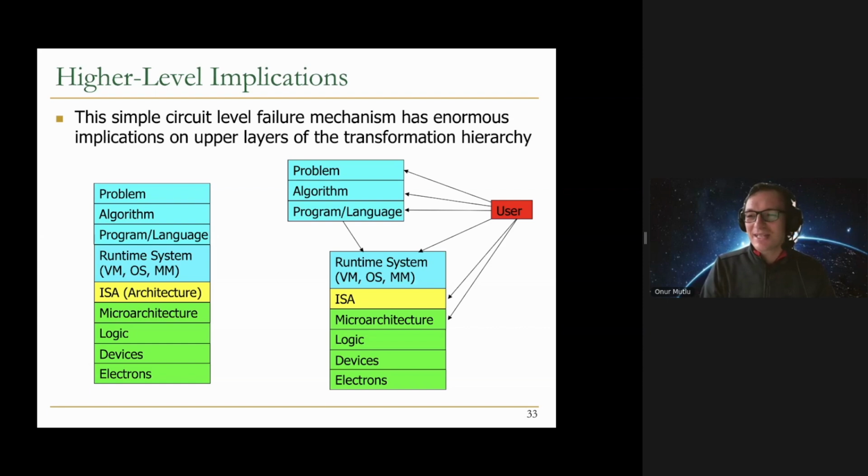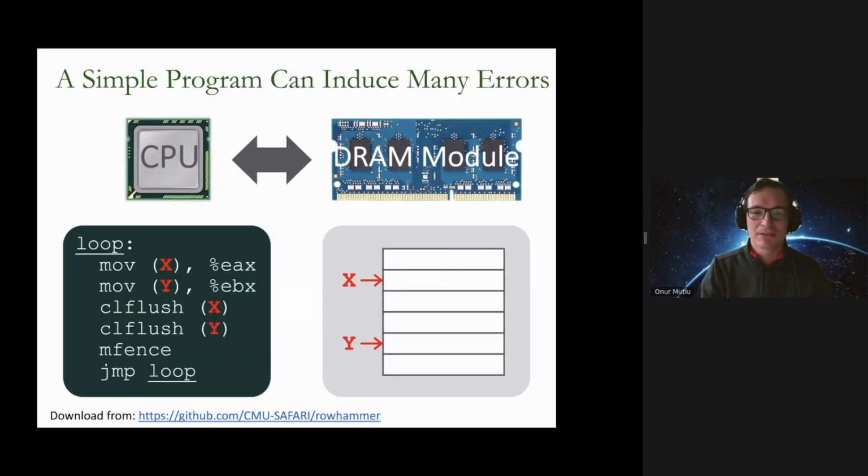Essentially, DRAM, as I said, is not special because it's not immune to read disturb, but it is very special actually because whatever bit flip you get in DRAM directly gets exposed to your programs. It directly gets exposed to your data structures, operating system, applications. As a result, you have essentially no protection against these bit flips. So certainly you can get data corruption. Your system can halt for some reason because you get a bit flip on a critical data structure. And worse yet, somebody can actually take advantage of these bit flips to take over your system, as we will talk about. And this all happens because you can induce these bit flips predictably in software with user-level programs. So this is the user-level program that we released when we actually published the paper.